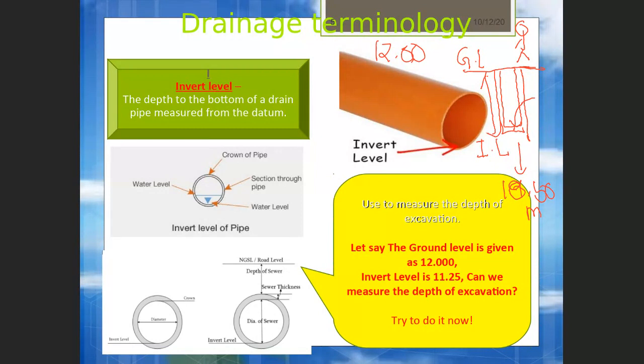So basically, in order for you to get the depth, you have to take ground level, deduct invert level. So you get the depth. Yes, Moses, correct. Okay, thank you very much. Just want to make sure that you are there, because just now it was very quiet.